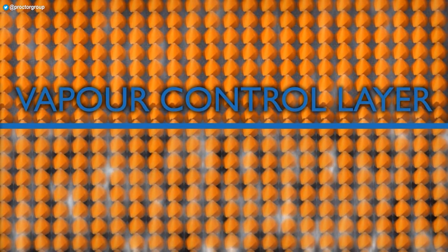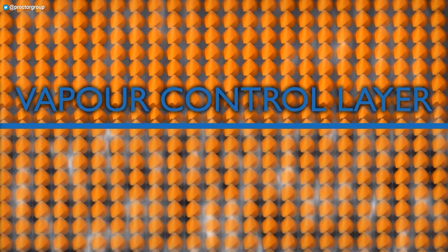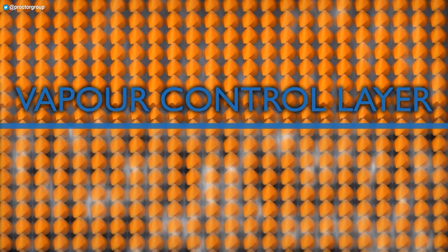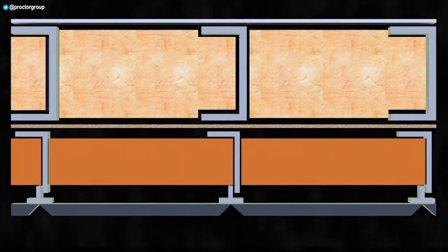Most building materials are unable to stop vapour diffusion completely, and therefore building science uses the term vapour control layers, suggesting that they will control, i.e. slow down, the process, but will not completely prevent the movement of water vapour. Low permeability materials are those which can significantly slow down vapour diffusion.